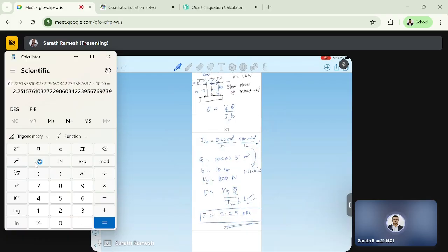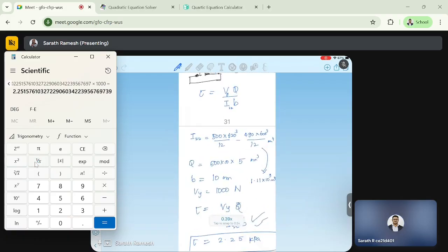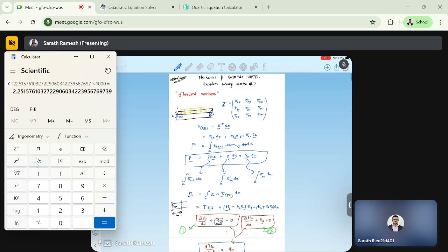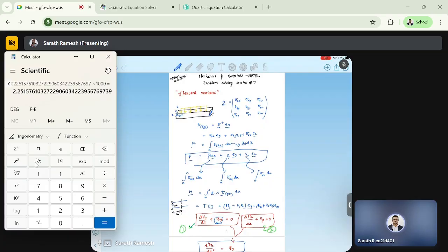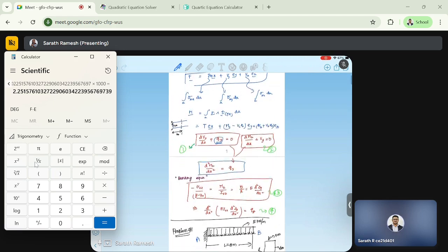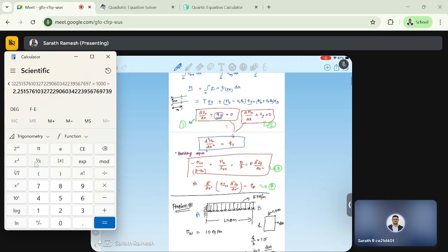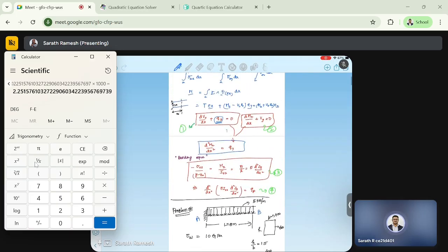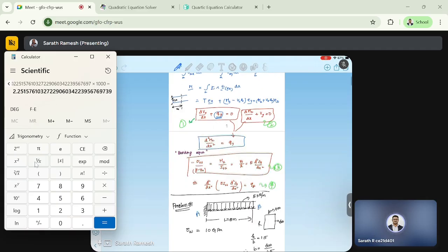Right, so with this I'll stop for today. I'll just quickly recap whatever we have seen so far. First, we started with how to solve a boundary value problem related to flexural members. Flexural members are members subjected to a transverse load that will cause bending in the member. It's going to produce the deflection and the rotations. We saw the basic equilibrium equations that help us solve the problems, and using compatibility and strain displacement, we got the bending equation.